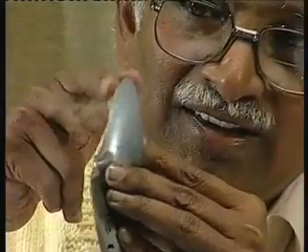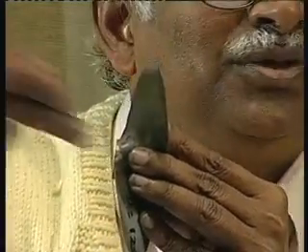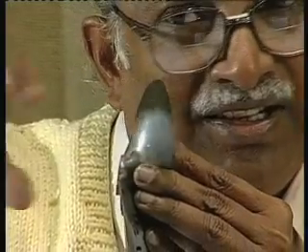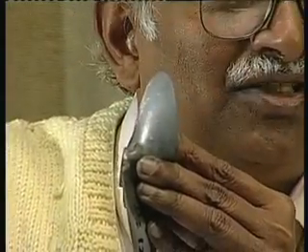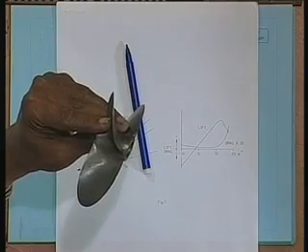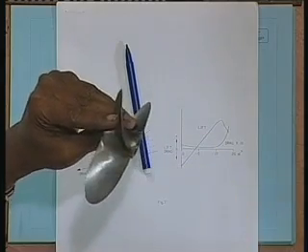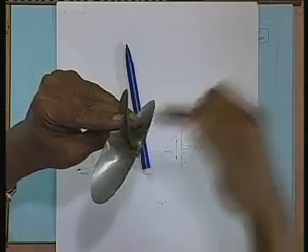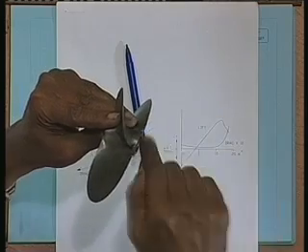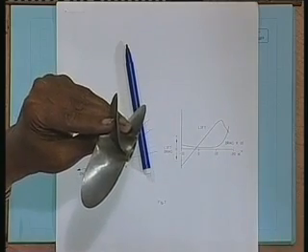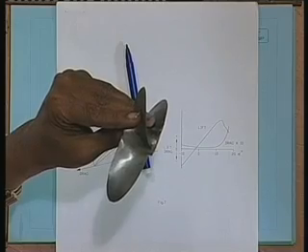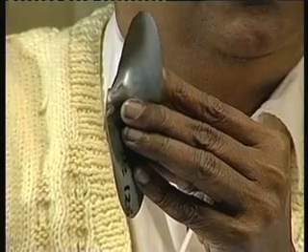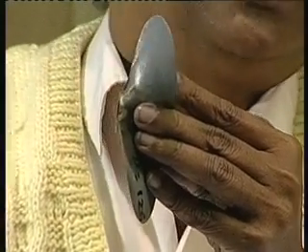There will be a drag in the same direction, but a lift in the opposite perpendicular direction. So, if you look at this lift which is going like this, most of its component is in the axial direction. If I now compute it, one in this direction, one is this direction, most of it is this way, because the perpendicular is making a very small angle to the axis of the propeller. Does it mean that the thrust and the lift are acting in the same direction? Thrust and lift are not different. The axial component of lift is the thrust.